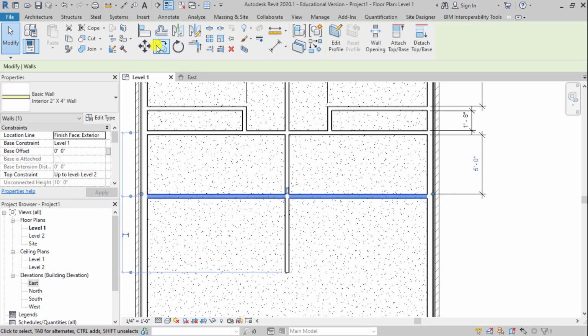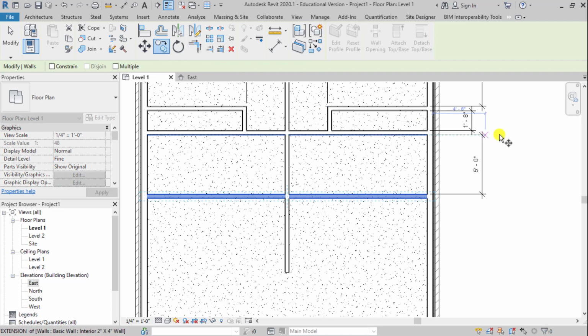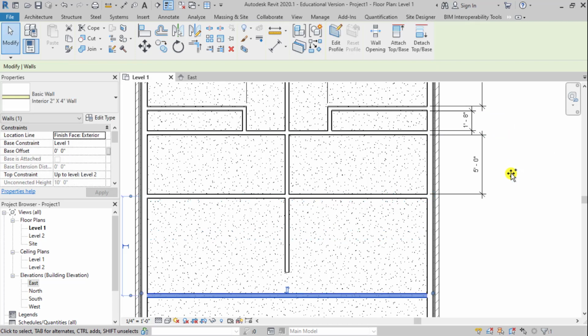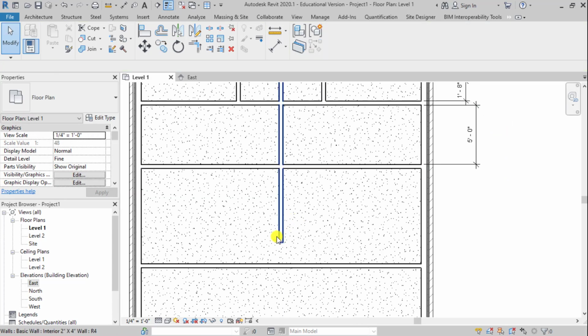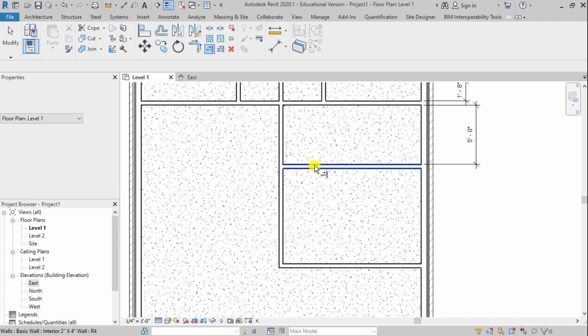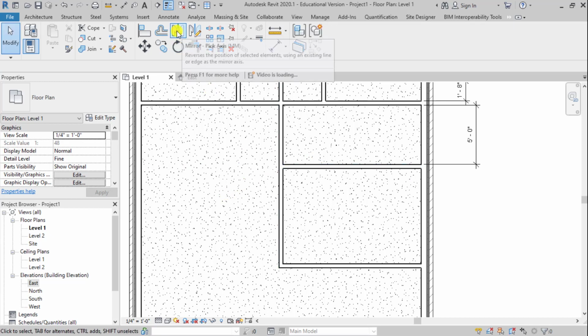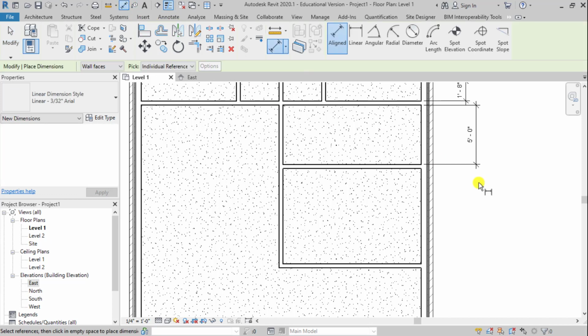I'm going to take that wall, I'm going to copy it again, and I'm going to go down 8 feet 4.5 inches, enter. Now I can see that this isn't long enough, which is fine. I'm going to select my trim extend, aka chamfer, picking what I want to keep, and I can see I get that nice little blue hidden line that shows me my result. Now I'm going to trim. I'm going to use this as my cutting edge, and I'm going to pick what I want to keep. Opposite of AutoCAD. In AutoCAD, we pick what we want to get rid of. I'm going to dimension my mechanical room,